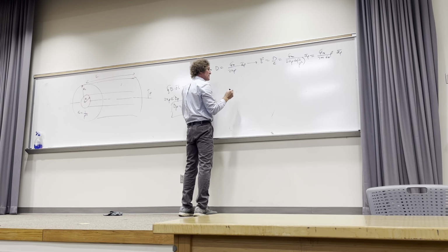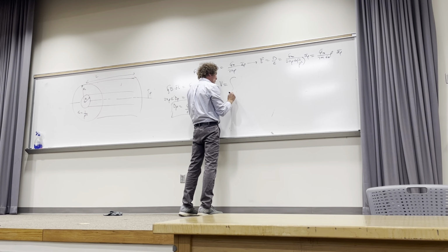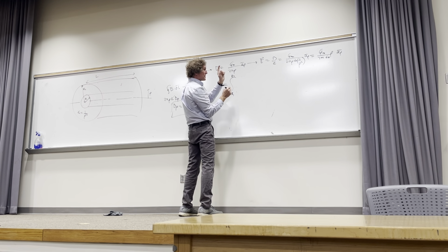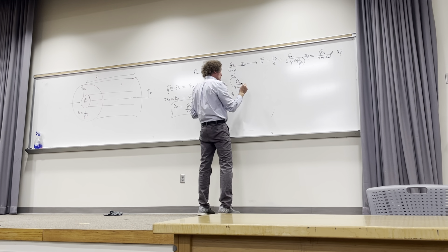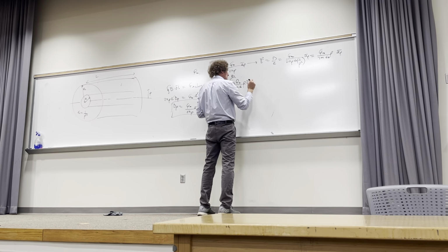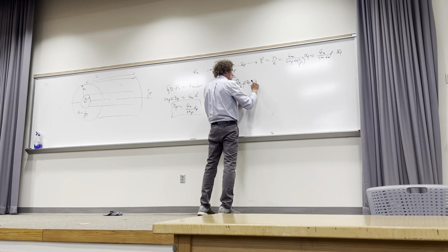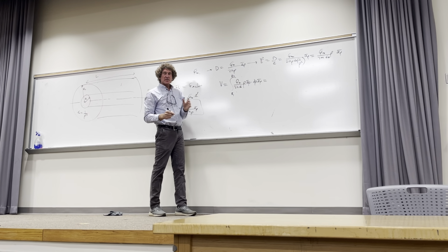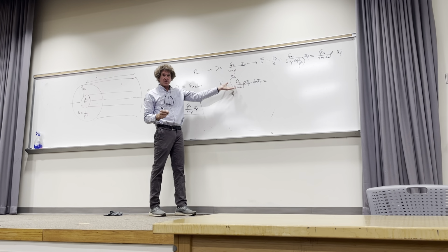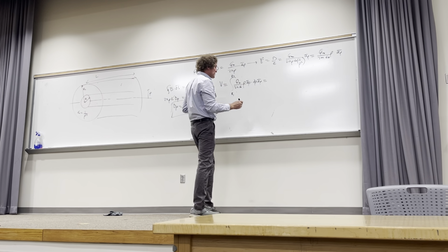Once I get the E field, I've got to get V. So V in magnitude will be the integral from R1 to R2 of the E field, which is Qm over 2 pi epsilon naught rho a rho, dot dl. In this case, dl is just d rho a rho. If you didn't put the dot product and things like that, I winked at it this time. I wasn't a stickler for it, but I need to see that you understand you're doing an integral of the E field to get the voltage, something that indicates you know what you're doing there.